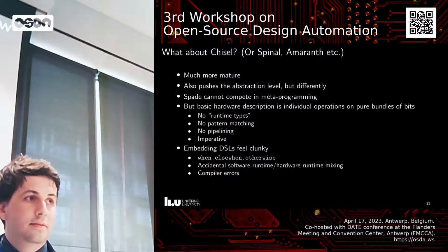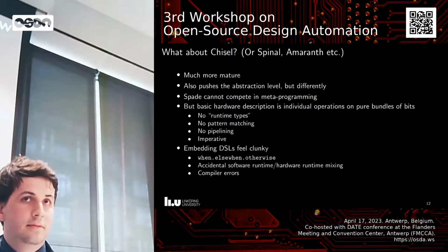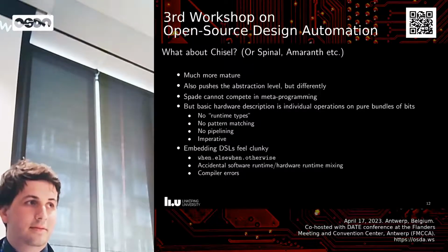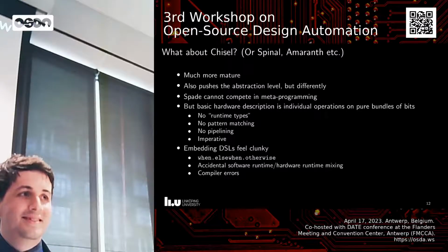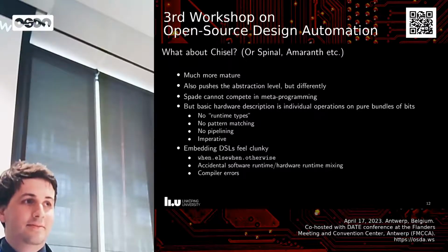Another place where you use type classes is if you think of a large system that has control and status registers floating all over the place in different modules. Ultimately, that's a global space of control and status registers, and plumbing it through module interfaces is often extremely messy. Again, type classes completely solve that problem for you because you can hide the plumbing using the monadic type that you have. So we're complete believers in very strong polymorphic typing in hardware design languages. I agree.